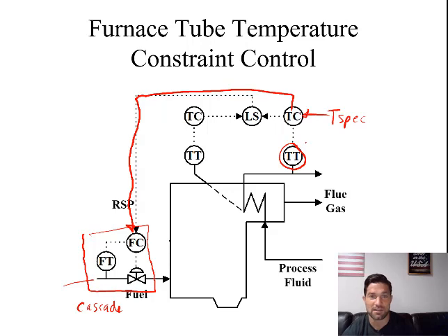of the product decreases, the primary control loop is going to ask for more and more fuel. As more and more fuel is fed to the furnace, the temperature of the furnace is going to heat up, and the temperature of these tubes can get hot. If the tubes get too hot, it can cause wear or potential safety dangers associated with these tubes failing. To prevent these tubes from failing, we're going to incorporate another control loop.